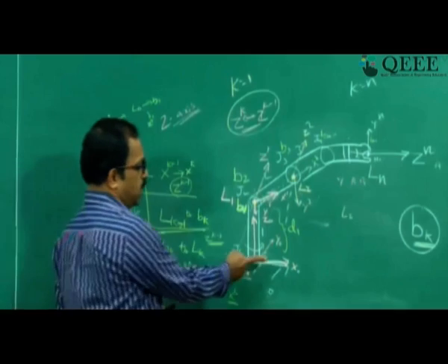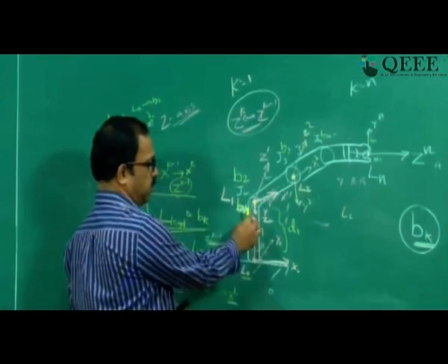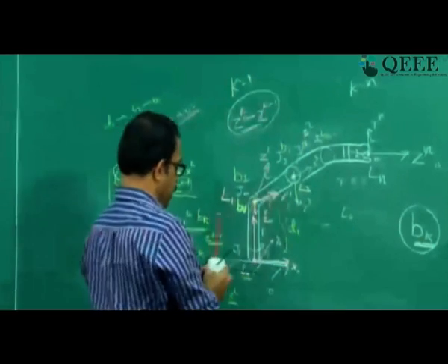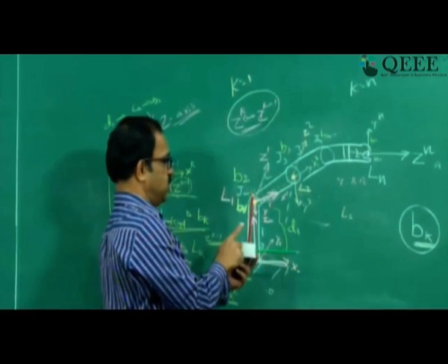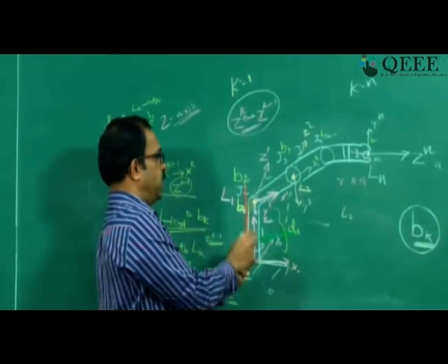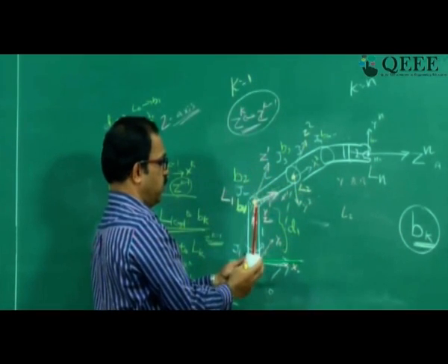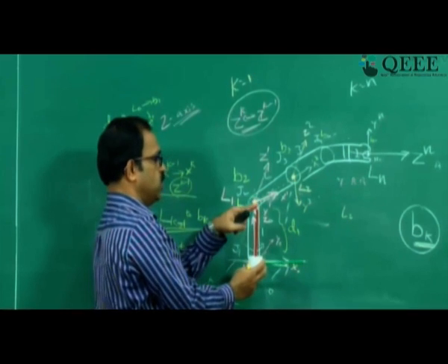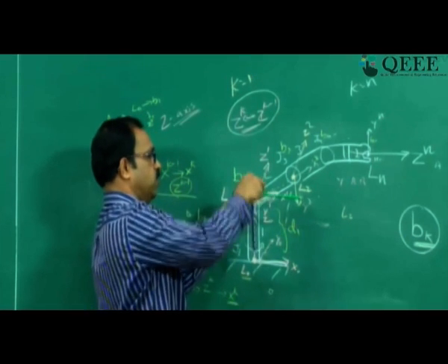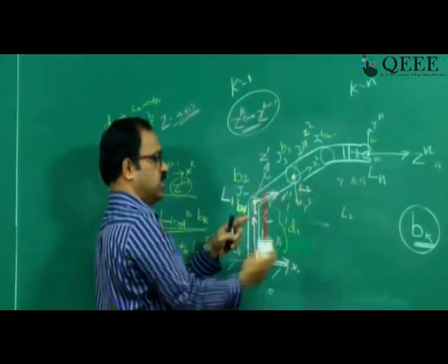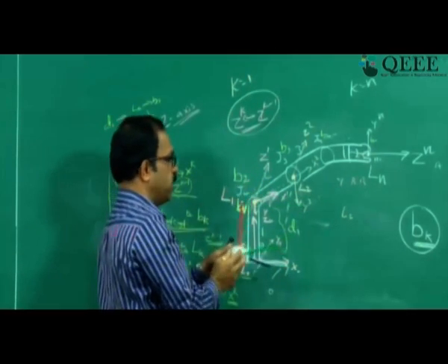You can see here, this z-axis is like this, and this z-axis is like this. So there is a rotation of 90 degrees for this to become like this. So this joint axis has changed by this much. That is the alpha, and you measure about this x-axis.